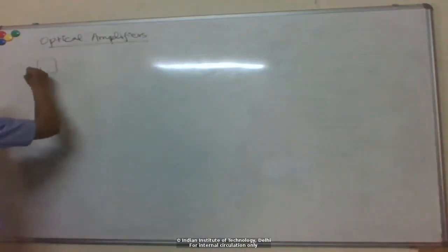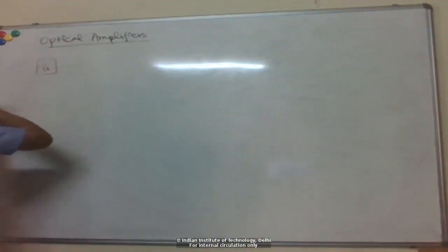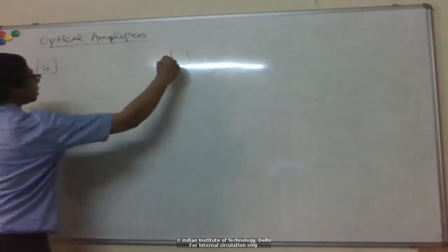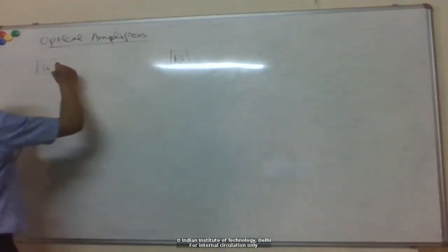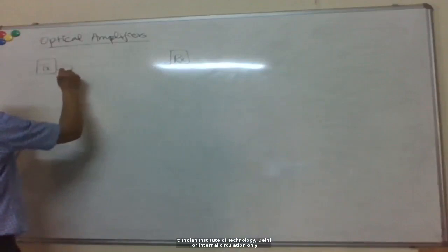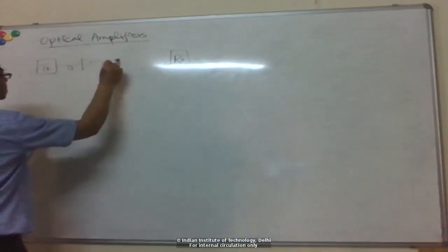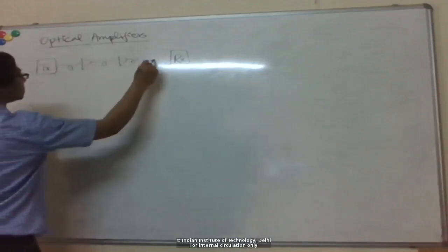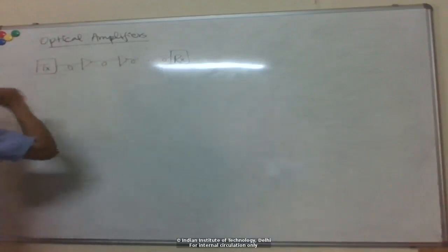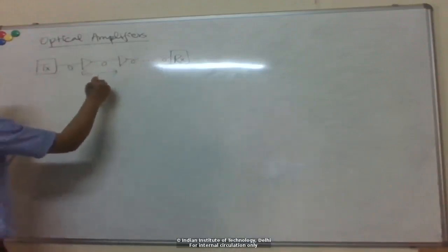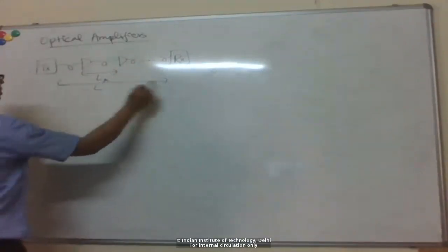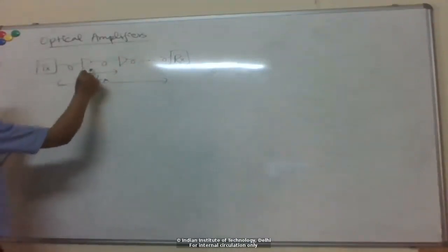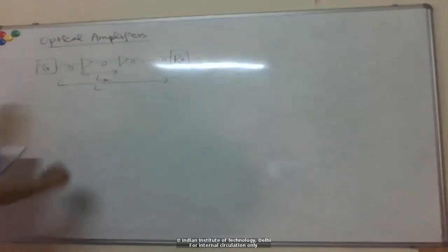Okay, so optical amplifiers are used in various places along the link to boost my signal, right? Of course, for a very long length, you can imagine that the signal is getting attenuated a lot, so I can insert amplifiers periodically, right? As we've discussed at some previous points in the course, for total link length of L, we could have amplifiers every LA length.